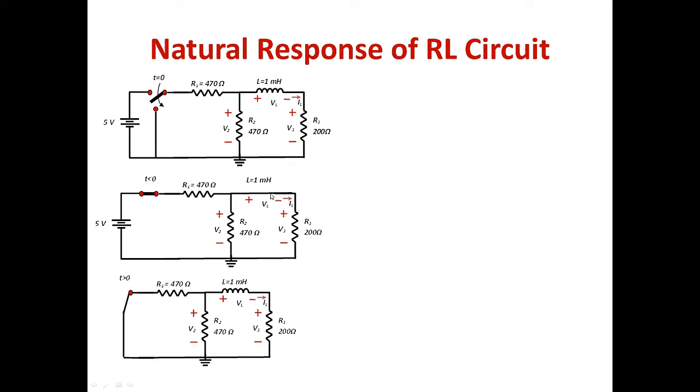The reason is that the current has to be continuous. If the current is not continuous and doesn't have a finite derivative, the voltage across the inductor is going to be infinite, and that's going to basically burn the whole circuit. So it doesn't work. We have to force the current before switching and right after switching to be the same. It's a continuous current.